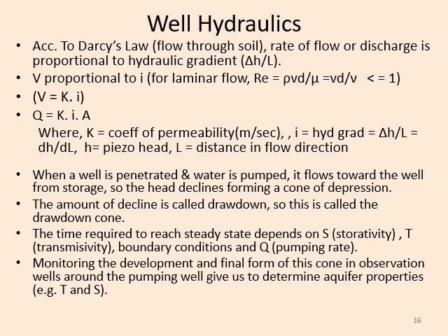The time required to reach the steady state depends on the aquifer characteristics, properties like storativity, transmissivity, the boundary conditions and the pumping rate. Monitoring the development and the final form of this cone in observation wells around the pumping well gives us the determination of aquifer properties, which is mainly storativity S and transmissivity T.